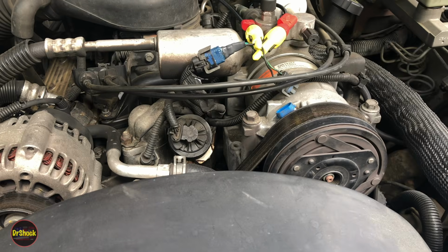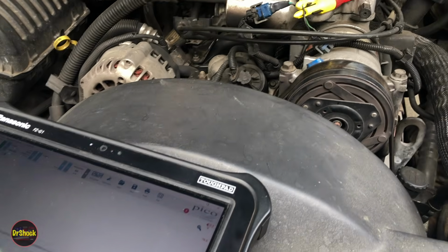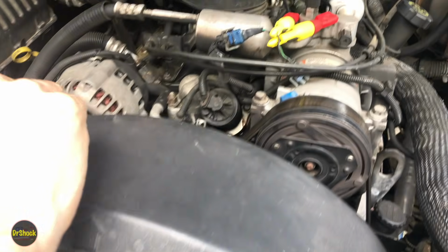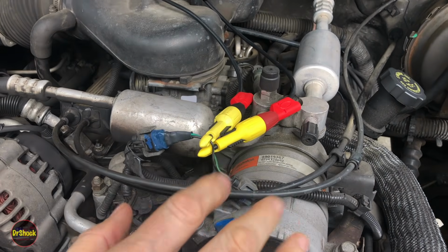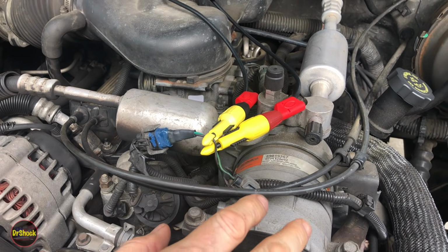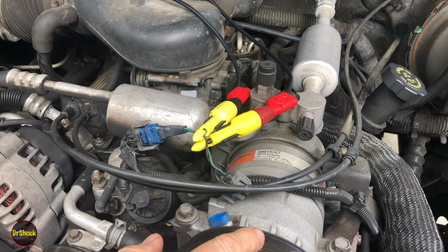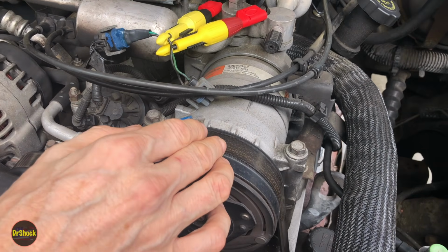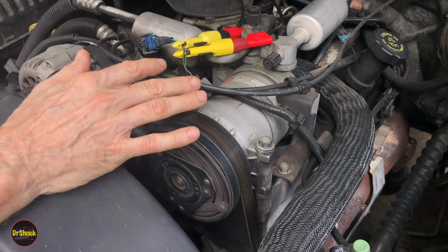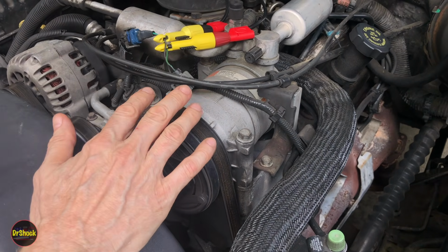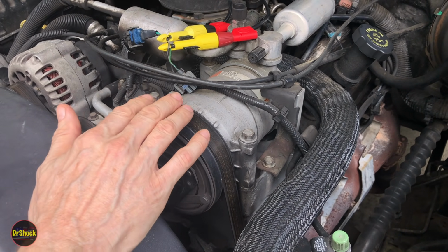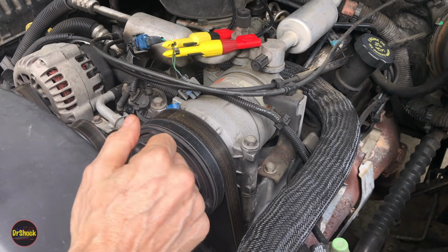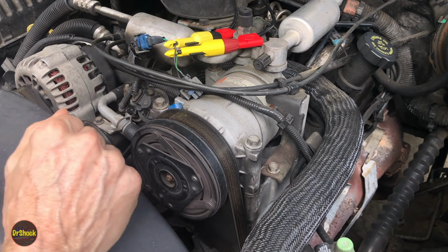So what's the repair here? Well, the repair here is going to depend on a couple of things. I'll give you my 2 cents worth. If this is an aftermarket AC compressor that you have on your truck, then my advice is to replace it, put a genuine OEM one on there to repair this problem. But this is an OEM GM compressor, so there's 2 flavors of this. This one here, this just bare aluminum, is a new type. If it's painted black, it's going to be remanufactured.